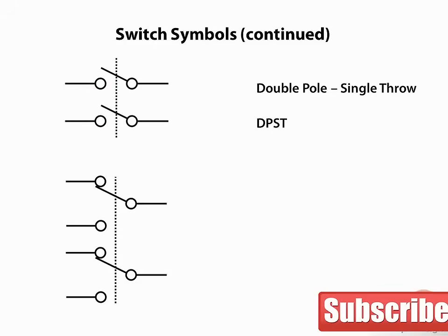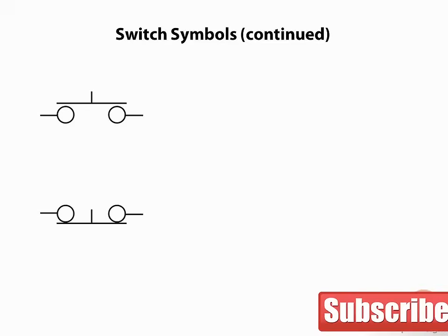What would you say is the configuration of this switch? It is a double pole, double throw. Two circuit commons selecting two possible contacts per common. As you can see, we can build up switches, at least schematically, for any number of poles or contacts we need. Push-button switches are also quite useful. They control their contact closures by push action rather than toggle action.